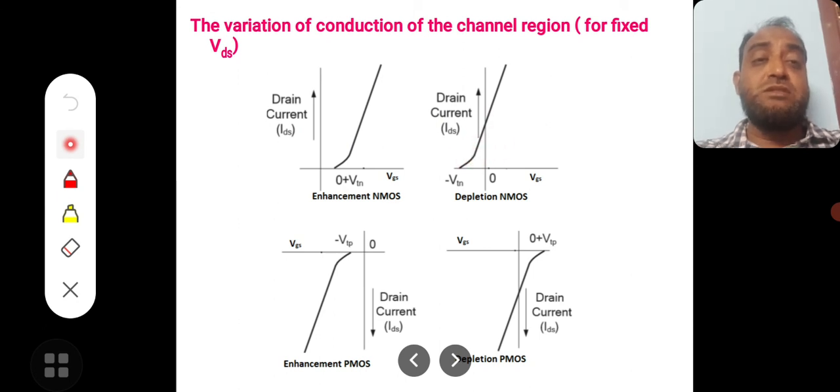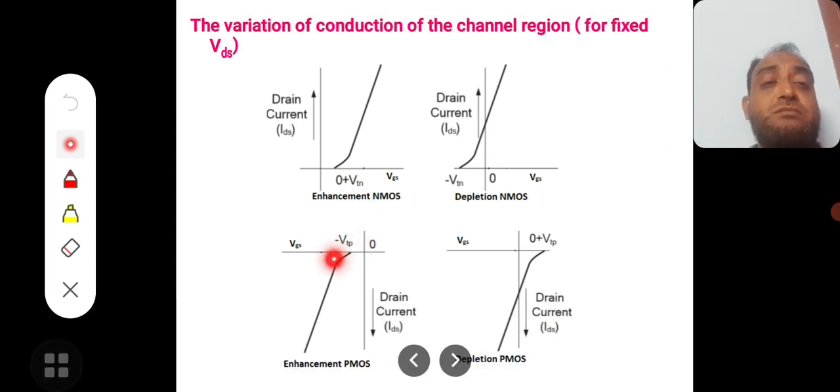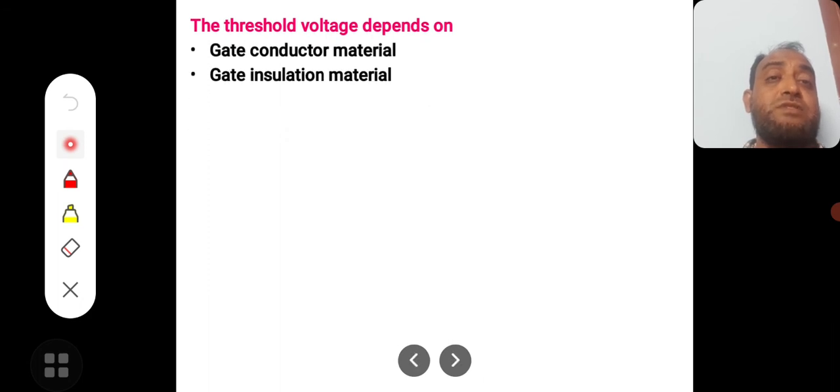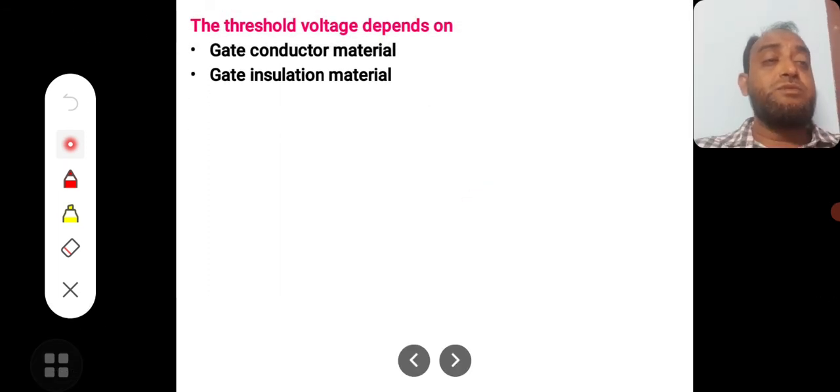Whereas PMOS behaves similarly, exactly reverse to the NMOS device. So the characteristic curve, which is in quadrant 1, has now become in quadrant 4 with the same parameters, and here also the same. So these are the electrical characteristics of the device. I hope you understand the topic.